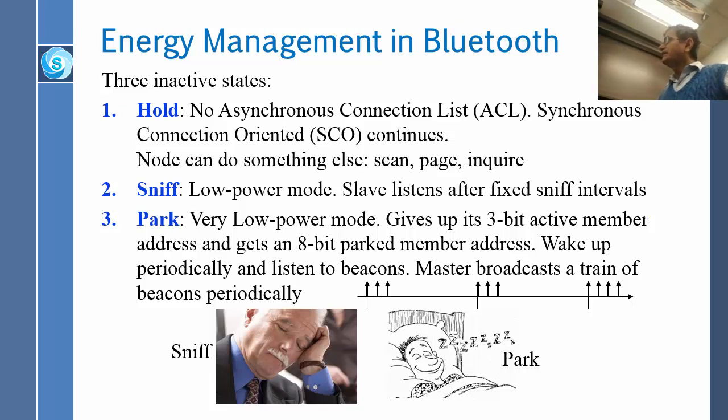This is the sniff state, and hold is simply not active on the connection except for the audio. Everything else is discontinuous. Of course, no audio can happen in the other 2 states. You cannot be sniffing and doing anything like audio, or in the park state. Only in the hold state can you do audio, but not any other data.